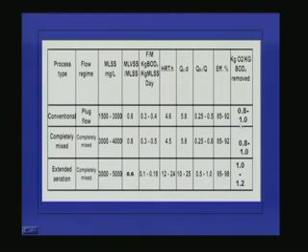And if you go for a conventional activated sludge process with a CSTR flow regime, that means a completely mixed flow regime, the MLSS concentration we usually keep in the range of 3000 to 4000 milligram per liter. Here also the MLVSS to MLSS ratio is 0.8 and the food to microorganism ratio we can change from 0.3 to 0.5 depending upon the type of system we are adopting.